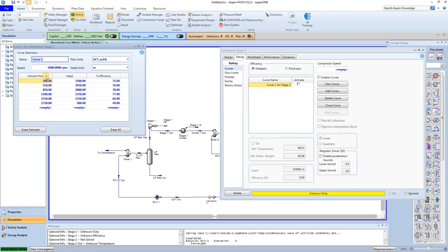Please make sure you use the correct units for all the curve table variables, and that you set the unit before entering the curve data. To guarantee proper units and data, set the default simulation units to the SI set while entering the curve data. This will maintain consistency between the SI input data from the table and the SI preferences in the curve input.